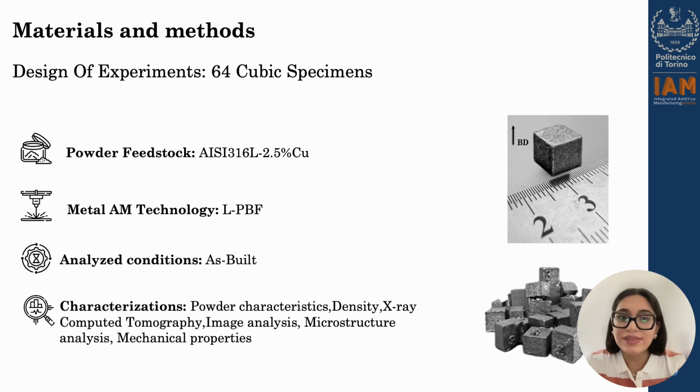As-built samples after the LPBF process were characterized in terms of residual defects by three techniques: Archimedes method, image analysis, and X-ray computed tomography. And at the end of this research, microstructure and mechanical properties of some of the optimum samples have been analyzed.